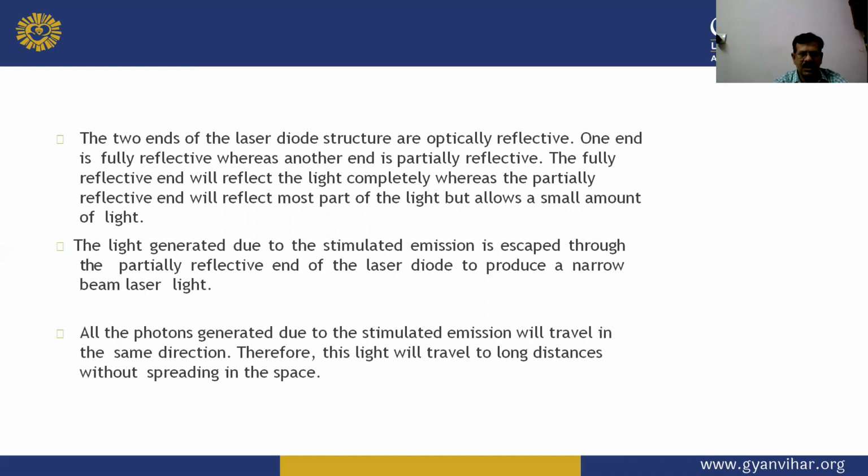The light generated due to the stimulated emission escapes through the partially reflective end of the laser diode to produce a narrow beam of laser light. All the photons generated due to stimulated emission will travel in the same direction. Therefore, this light will travel a long distance without spreading in space.